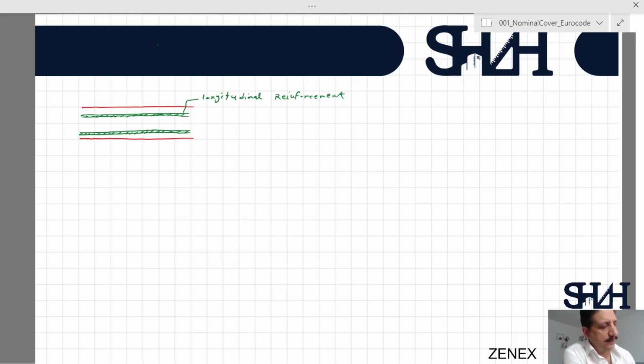We have reinforcement in compression as well, but mainly for tension. And also we have the shear reinforcement, which is called stirrups. They are designed for the shear force of the element against tension in other planes.